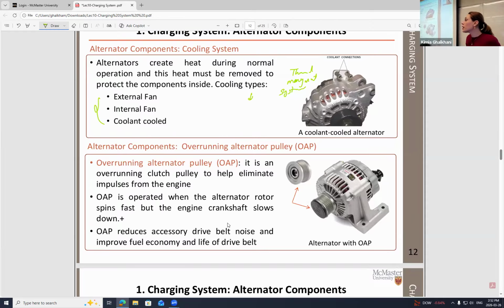And passive cooling is another method of cooling, such as phase change material, which is like a wax we apply around the battery. And why do we say phase change? Because initially it's solid. As soon as the temperature inside the battery goes up, that solid will change to liquid. That's why we call it phase change material, or PCM, which is the coolant technique. We call it passive cooling, and so on.